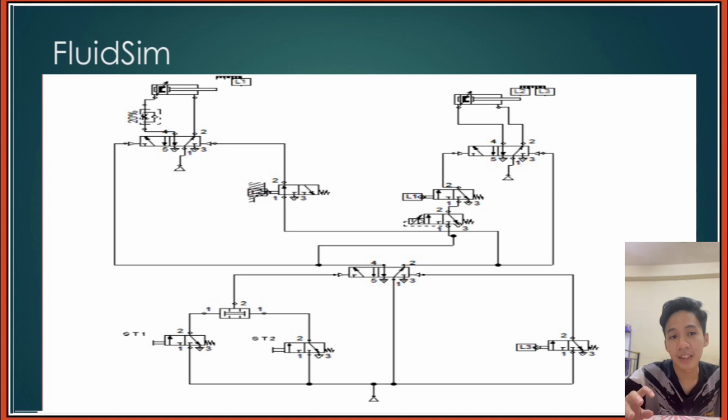After both are pressed, the valve in the middle will trigger and move to the right side, and then the clamper will extend because air is supplied. The valve on the clamper is port 14.